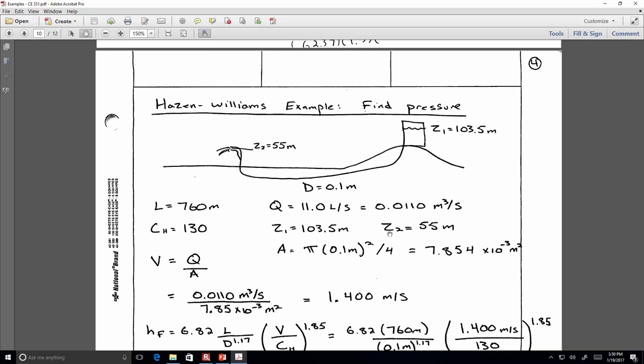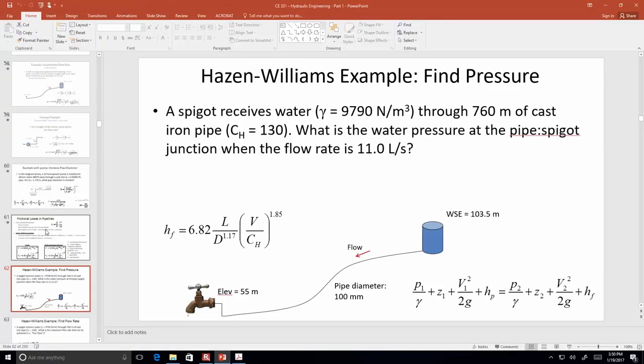But if you've got only 2.9 minutes to come up with an answer, then the Hazen-Williams equation will do a great job, and it's pretty direct. But the main reason why we don't always use it is it's not as accurate. And also, there are limits on the range of conditions that it can be applied to.